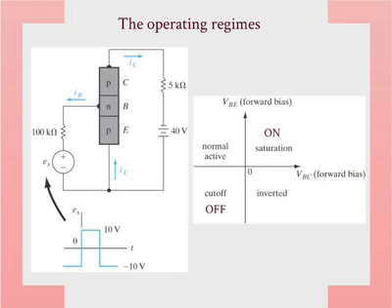So what I'm trying to say is that if you put the input into the collector, then that collector is actually an emitter, if you want normal operation. In other words, you can switch this whole thing, if you rotate this by 180 degrees. That's basically what you're saying. And then it becomes a common base configuration, which we saw before.